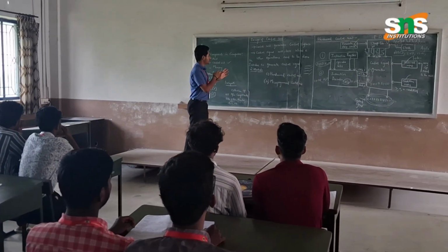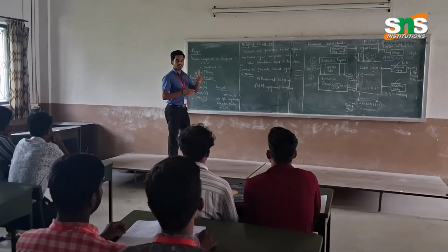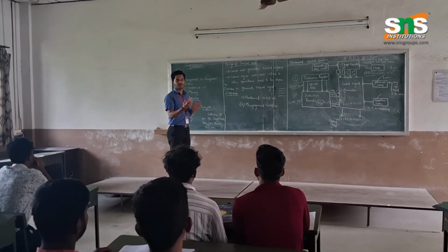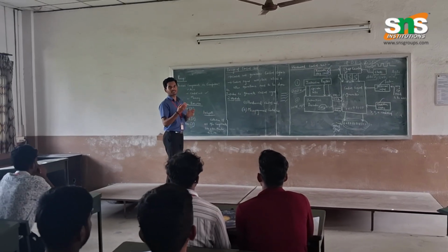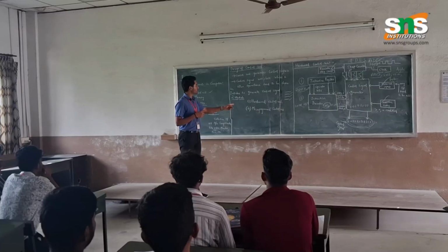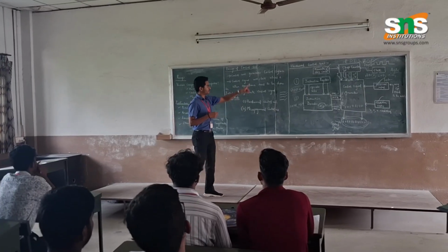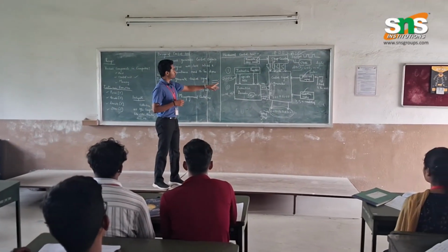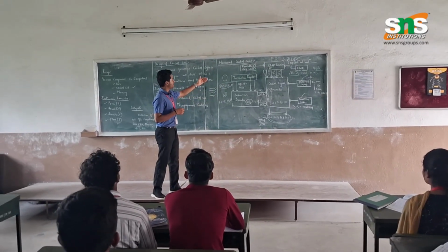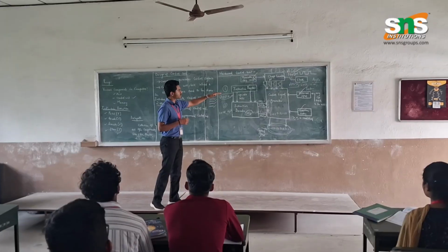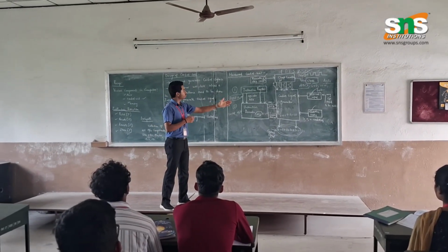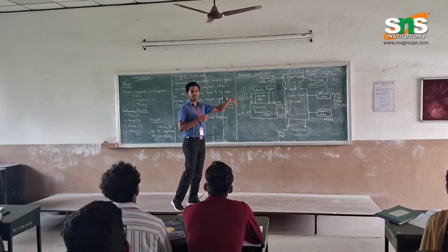So in order to generate control signals, there are two methods. Either it can be hardwired, that is direct flow of instruction through hardware components, or a microprogrammed control unit. And this diagram shows how a control signal gets input from the instruction decoder and other peripherals like the instruction register, external input, and condition codes. And based on the clock signal we give, it provides the execution outputs.